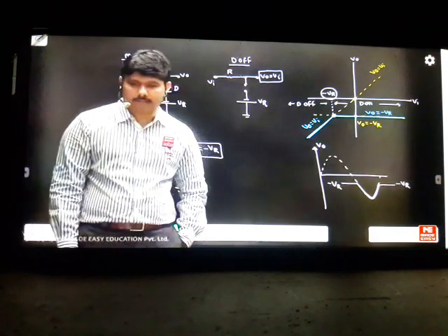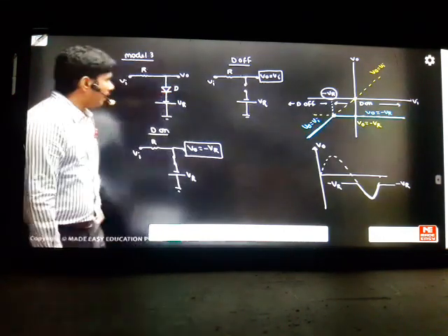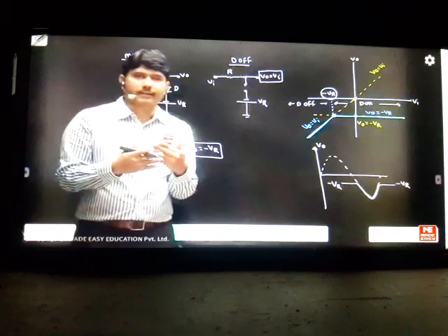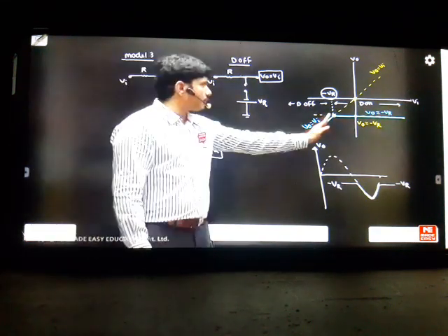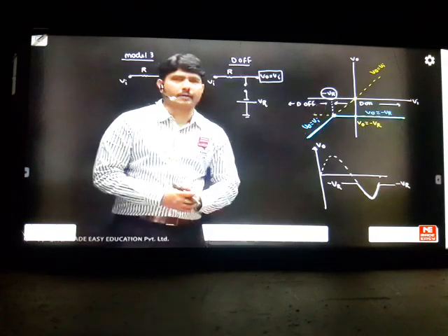How do you relate the diode with minus VR? Who is that? Ria. I think this is a reference here. On the cathode side we have a reference. With respect to the reference, the anode is the signal we applied. It can be more or less. We're just checking the values. Below minus VR, the diode is off. Above this, it is on. I'm telling this by seeing the anode and cathode positions.